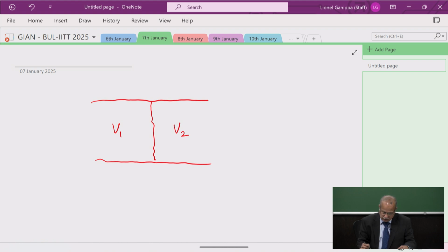So he proposed this hypothesis that the product of the velocity before and after is equal to the square of the speed of sound. He referred to the speed of sound because the speed of sound is equal to the square root of gamma RT. It is very much dependent on the local temperature, the local speed of sound.